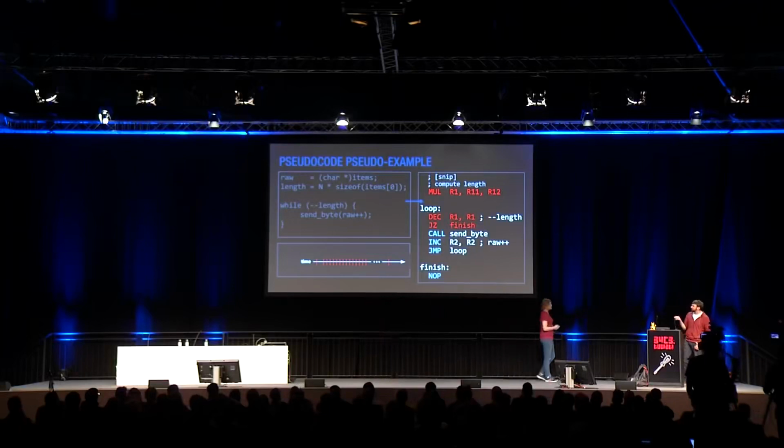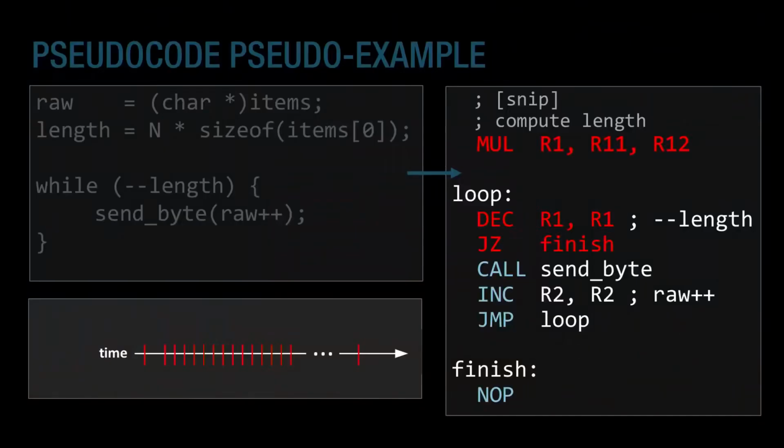Yeah, so this diagram just shows that this red line here, these are all the options we have to have a successful glitching attack. It's fairly spread out, but there are a lot of them. So this is the multiply; we've got one chance at that. Then this decrement happens every time around the loop, and we have lots of chances to hit that one each time. And then finally we have this jump when we finish the loop, and we only have one chance at skipping that step as well, because there's only one time that jump is meaningful, and that's when we hit 0.